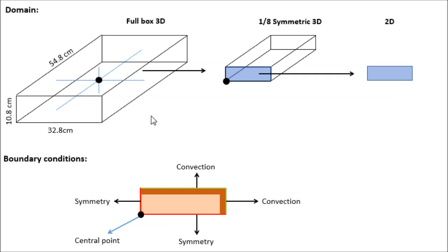So the geometry is regular. It means that the problem is symmetric. We can do the same exercise from the face in front and the opposite face, and the face in the top and the face of the bottom. So we have basically 3 symmetry planes, and we can take advantage of that. For example, taking only 1/8 of the geometry.